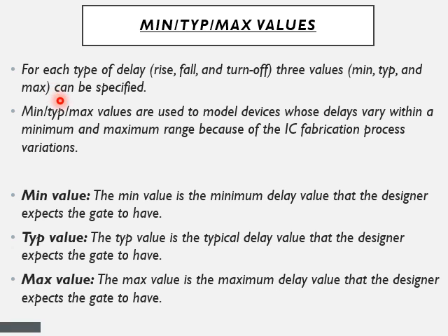These values are important in modeling of digital circuits such that we have a range of minimum to maximum values because of the IC fabrication process variations. Okay, finally the digital circuits that we are realizing or modeling using Verilog have to go for fabrication. The end product is the IC, which is fabricated in the foundries. So these foundries have various process variations, and to adapt to these adverse conditions, we have this relaxation of a range of values.